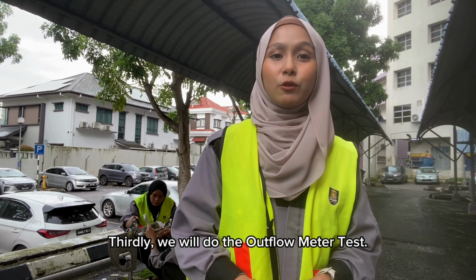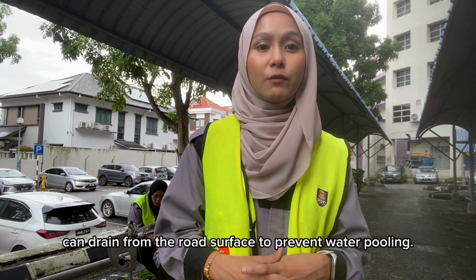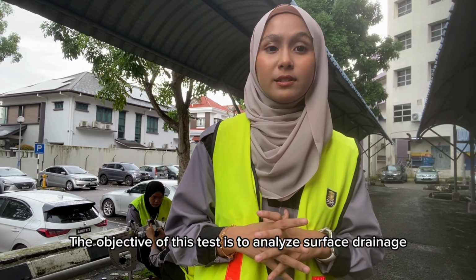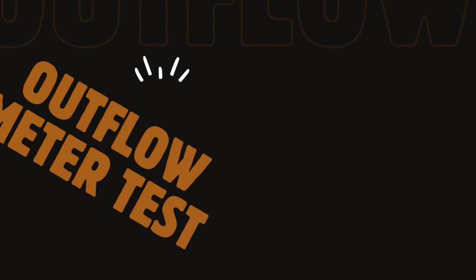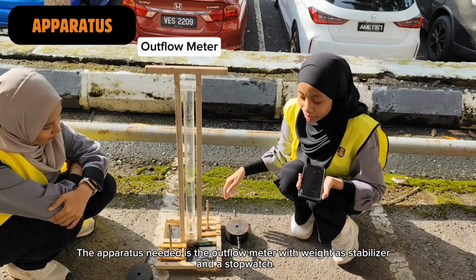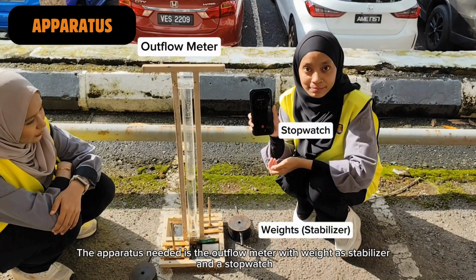Thirdly, we will do the outflow meter test. The purpose of this test is to measure how quickly water can drain from the road surface to prevent water pooling. The objective of this test is to analyze the surface drainage efficiency and identify areas prone to water retention. Apparatus needed is the outflow meter with a weight for stabilizer and a stopwatch.